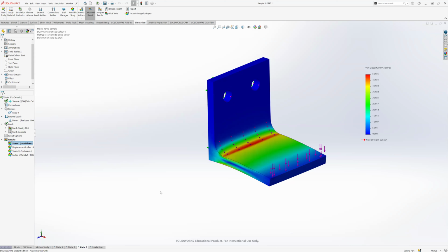So it's a decent quality. You don't have to really deal with too many problems. You have enough elements across the thickness. But then when you want to come in to certain components or certain areas, typically in a part or something, that's where mesh controls are really, really useful. So yeah, that's really nice. Any questions on mesh controls or running simulation with mesh controls?